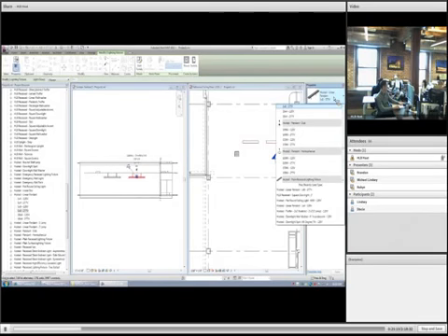The architect then decides, we want to move the public corridor to 10 feet. What type of indication will we have that they made that change and our fixtures are 2 feet off? What used to be the same ceiling is now changed. Yeah, it's just a verbal coordination.